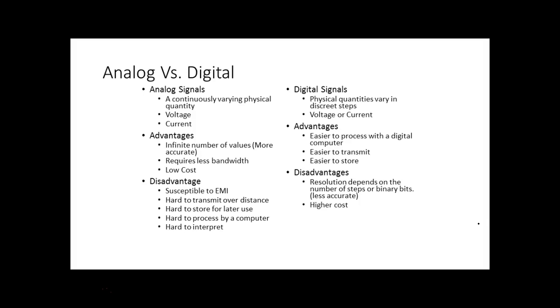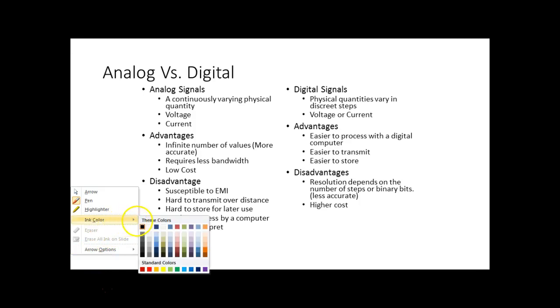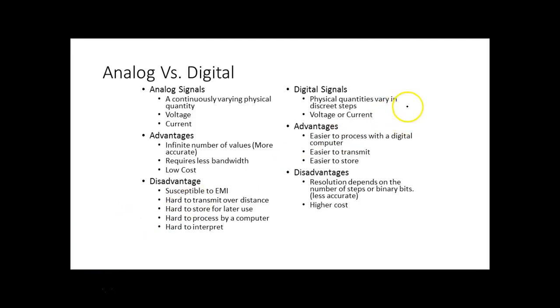It costs a lot. A lot of your A to D converters, by the way, I know the one on the MicroLogix 1100 is a 10-bit A to D converter. Now, what an A to D converter does is that we can take the information coming from an analog sensor and bring it into an A to D converter, and then it'll give us a binary number that's a representation of it. It'll never be an equivalent, right?